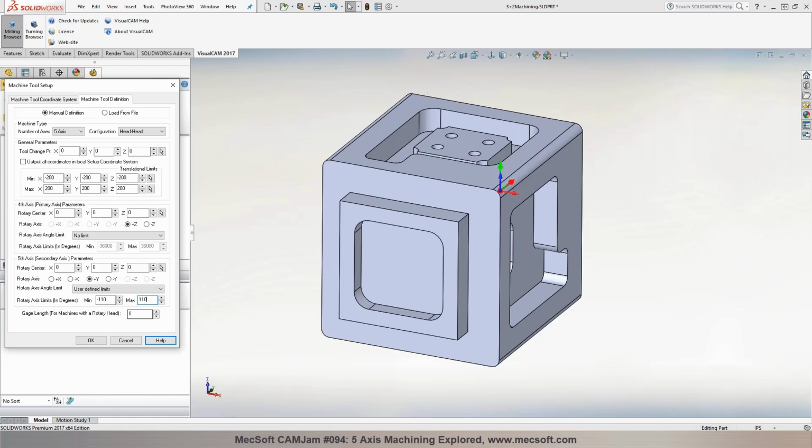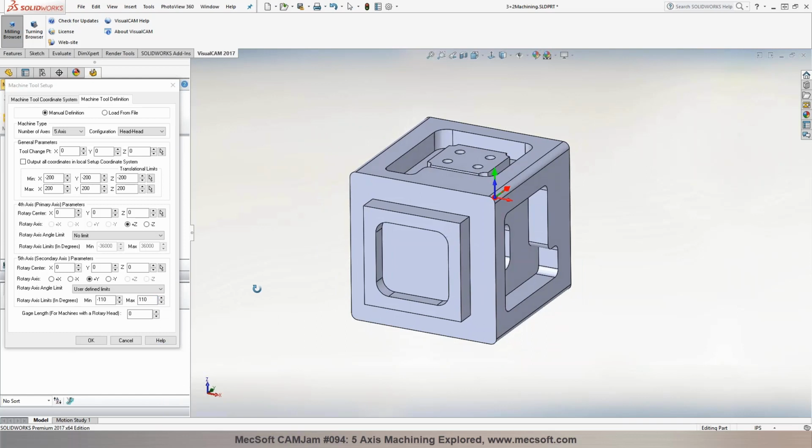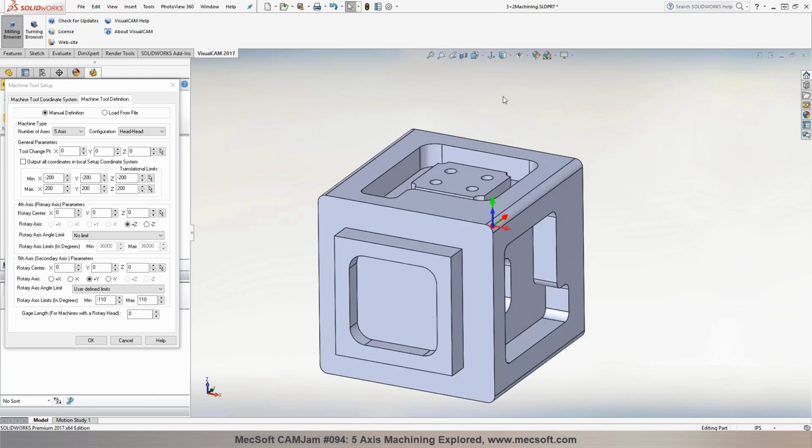Okay, yes, I understand. And I have to check really well the features of the machine in order to set those degrees and those features correctly in RhinoCam. Right, if you look at the machine tool specification provided by the machine tool vendor or manufacturer, they would tell you the rotary axis limits of primary and secondary, and they will provide you with most of the information.